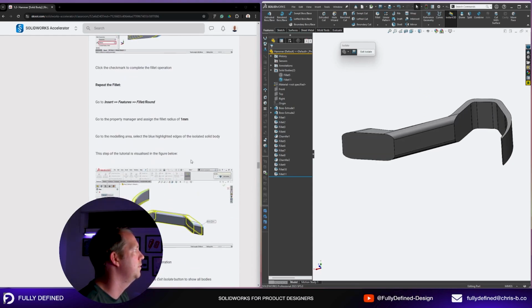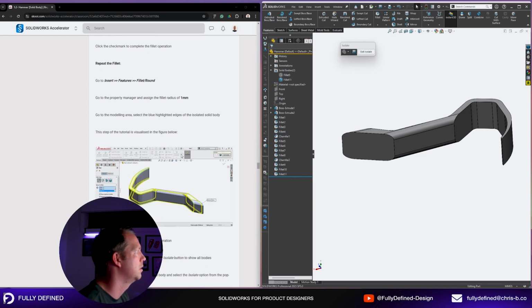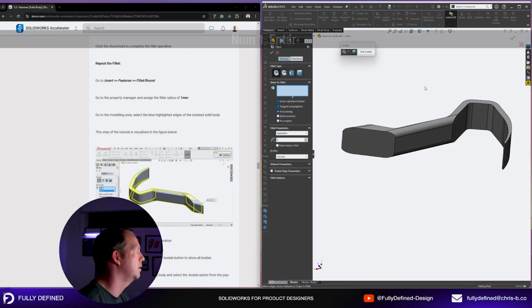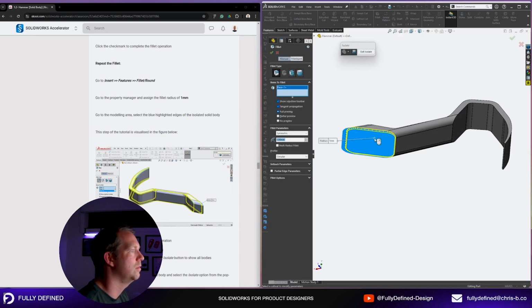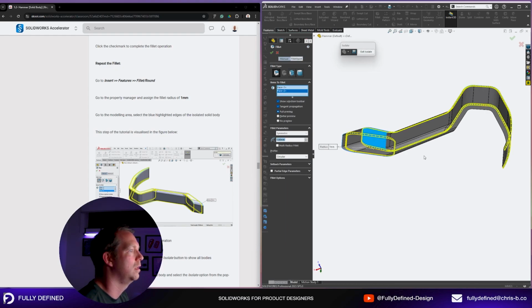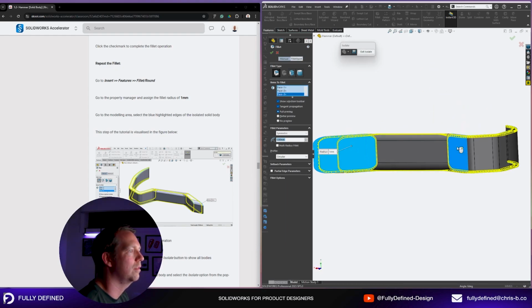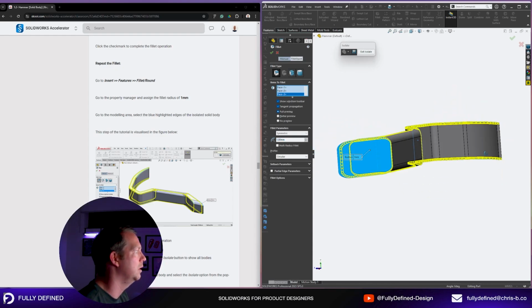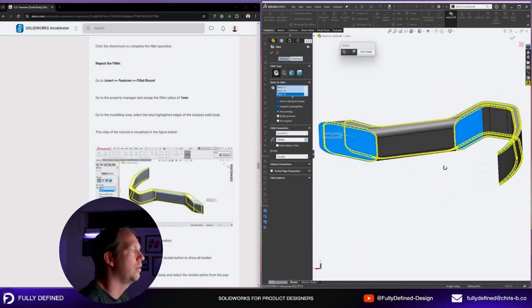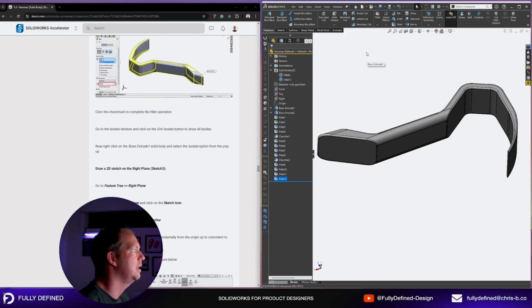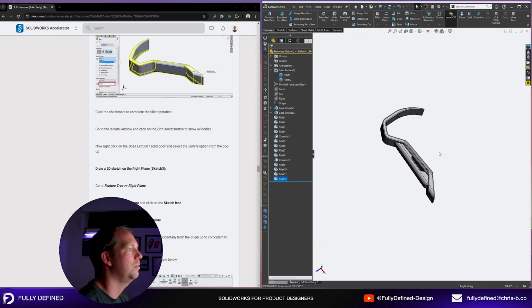And now a lot more fillets. Quite a few edges, or almost all the edges, which is fine. So it's going to be 1mm radius. I should only have to do a few selections, and it will go all the way around. So I can select 3 faces, and that's going to fill all the edges. Okay. Exit isolate. Show all the bodies.